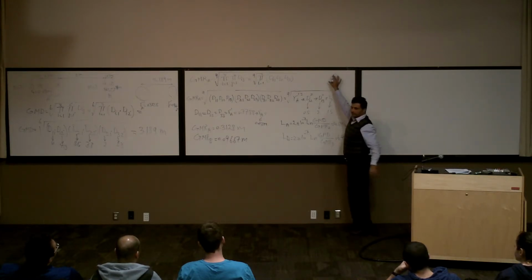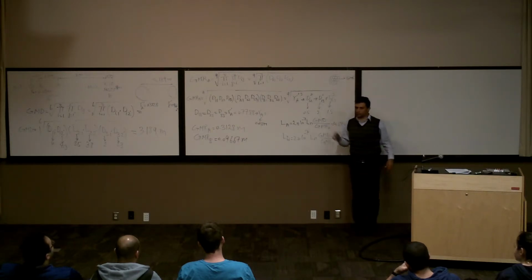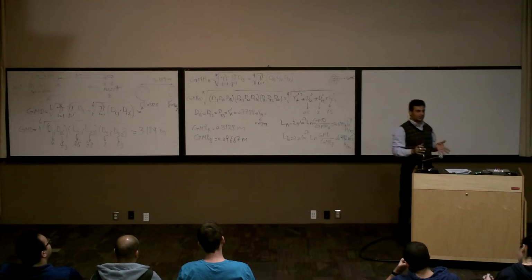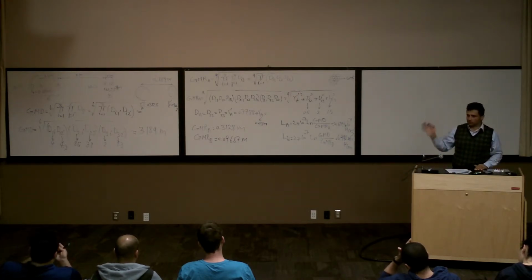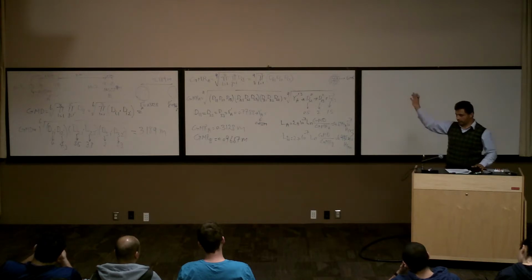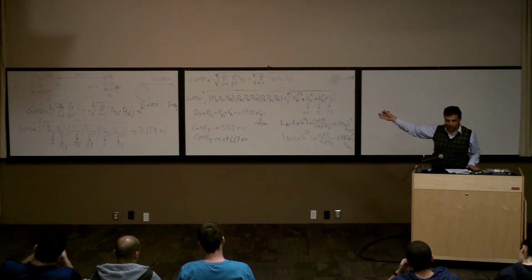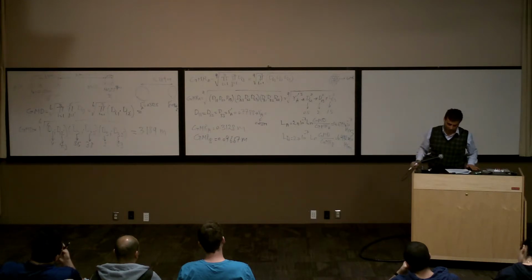And if you select this conductor, the GMR is given already. In reality, you don't need to calculate the GMR for the transmission line. But it is kind of a special project where you need to calculate the inductance for that system. You can use this equation to calculate the inductance.